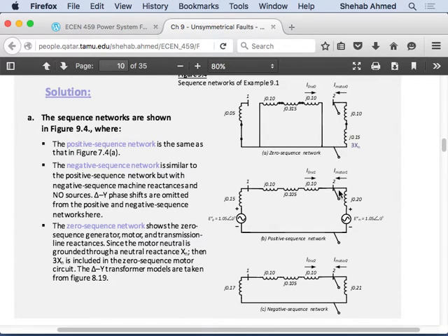So you go to every one of these circuits and you stop, put 2 pins like they have here, and then find a Thevenin equivalent circuit between these 2 nodes. What is a Thevenin equivalent circuit between these 2 nodes? And it's open here, so it's nothing here. So it's just these 2 impedances in series.